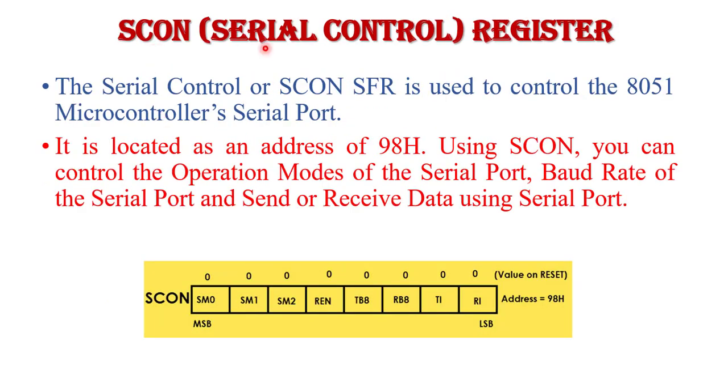Next is the SCON register. SCON stands for serial control register. The serial control special function register is used to control the 8051 microcontroller serial port. It is also an 8-bit register. The address of the SCON register is 98H in the special function register area in internal RAM. By using the SCON register, you can control the operating mode of the serial port, the baud rate of the serial port, and sending and receiving data using the serial port.